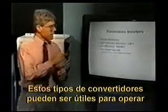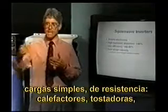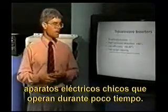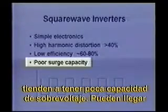These types of inverters might be useful for operating simple resistive type loads, heaters, toasters, small electric devices that might operate for a short amount of time. Their efficiency tends to be fairly low, 60 to 80% or less, and they also tend to have poor surge capability.